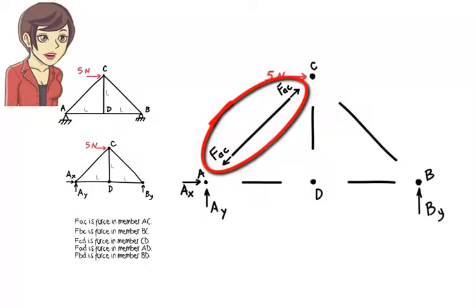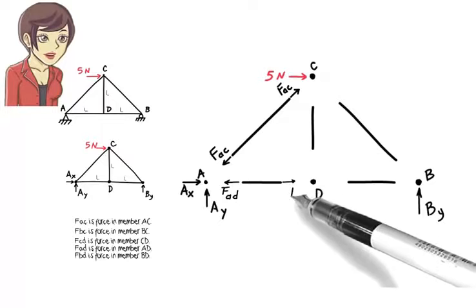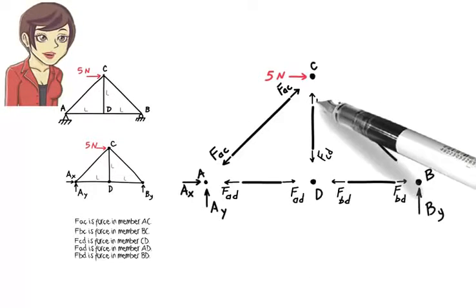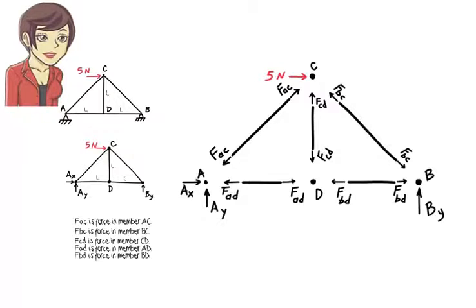The only force present in the diagram is the unknown tensile axial force in the member labeled FAC. I am going to draw the free body diagram for the other member segments in a similar manner. Each member is assumed to carry an unknown force. The member is assumed to be in tension. Now, let's draw the free body diagram for the joint segments. Let's examine joint A first. It connects members AC and AD.